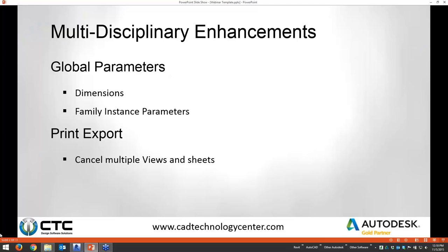So to start off with some of the new features, we have multidiscipline features, some architecture features, and then some MEP features. There are no structural only features in R2, just multidiscipline, architecture and some MEP. One of the first major things in the release for multidiscipline is global parameters. Global parameters are simply parameters that you can enter into a project that can globally change things in the project. For example, you can link dimensions to parameters to control them.